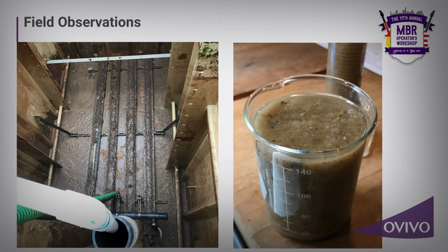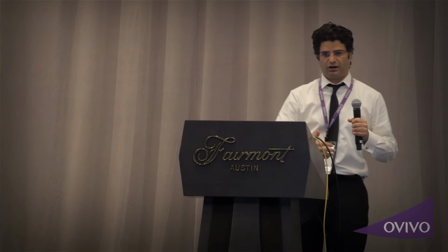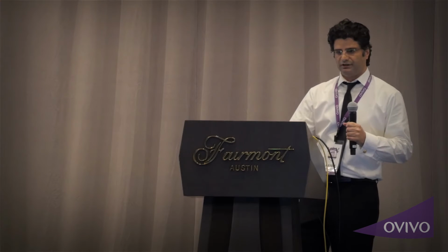On the left side is another picture, I like the left side picture. It shows the pre-aeration basin and the diffuser at the bottom. If you look, there is a layer of solids at the top of the diffuser, and this was caused by turning off the pre-aeration blower. The plant thought the high oxygen from the pre-aeration basin carried over to the anoxic basin. So they turned off the blower for a month or so to see if it could improve the denitrification.